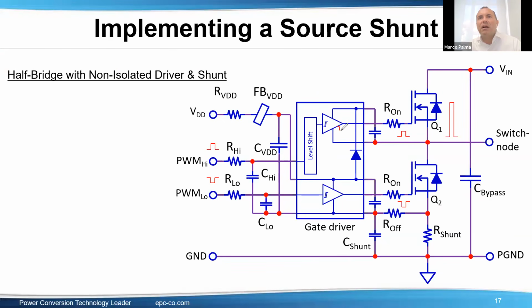Usually the gate driver has two outputs for the GaN FET, so you will have R off like this. And the main point of this was that in this case, you can have R off connected directly like this, because then you will have R off on the return. It's just a kind of technicality, but for sure you have both.